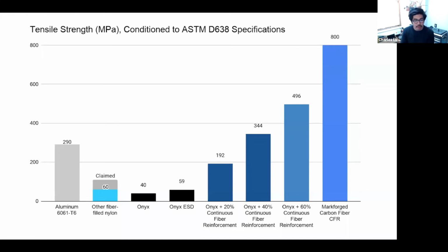On the industrial machines, like the X7 which we talked about earlier, this size machine, it has a laser calibration built in, and a stiffer gantry. That can get you probably on the order of 150 microns, plus or minus, with a 0.1% growth after that. Hopefully that answers your question.